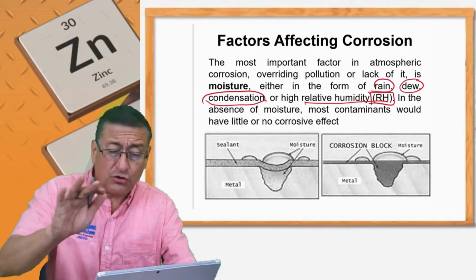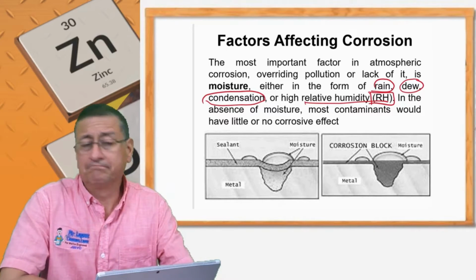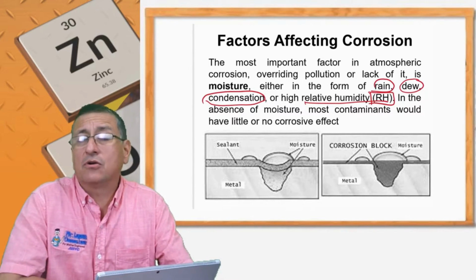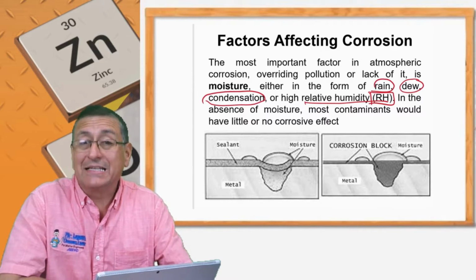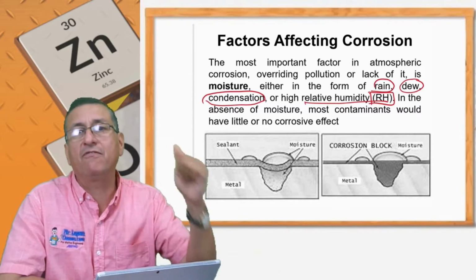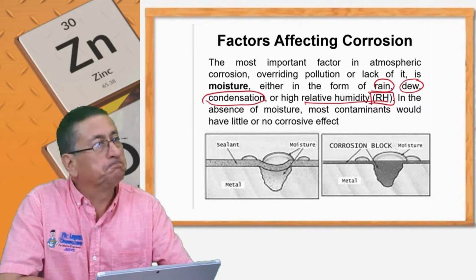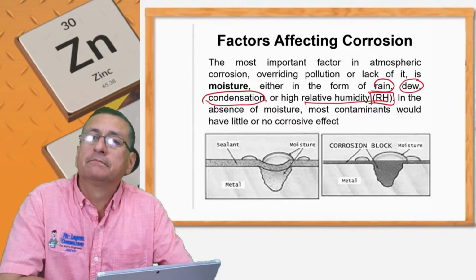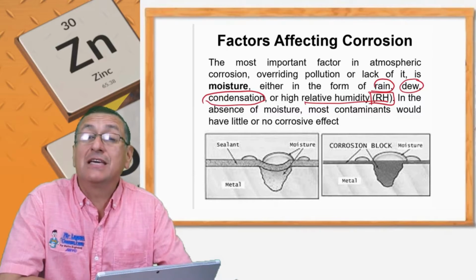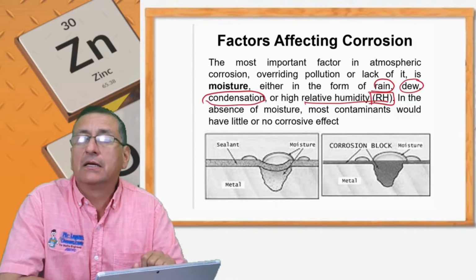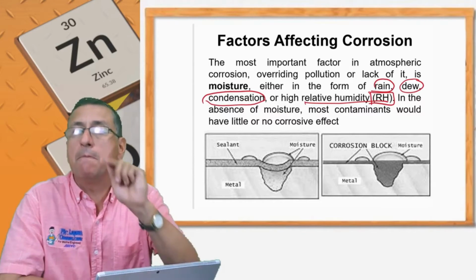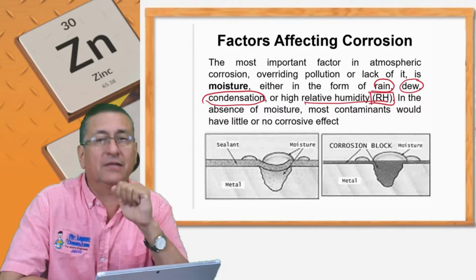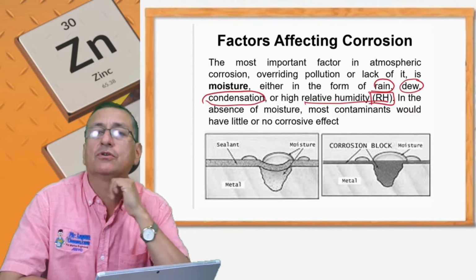If you don't have moisture, practically you don't have corrosion. The moisture accelerates the corrosion faster. Without moisture, it's difficult to corrode metals. For that reason, the secret is keep everything dry, keep dry and properly bonded. That's the secret to keep your boat in good condition.